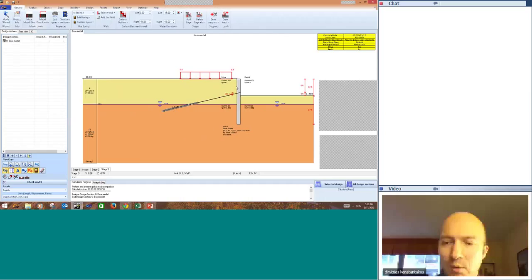So this looks like a better sized model. We can right-click, add stage, and I'm going to drag the excavation, the right, to elevation -21. Now on the yellow table, we see that for the water assumptions, we're assuming hydrostatic in our analysis. Apparently this is not sufficient, and we're also assuming active earth pressures Ka.